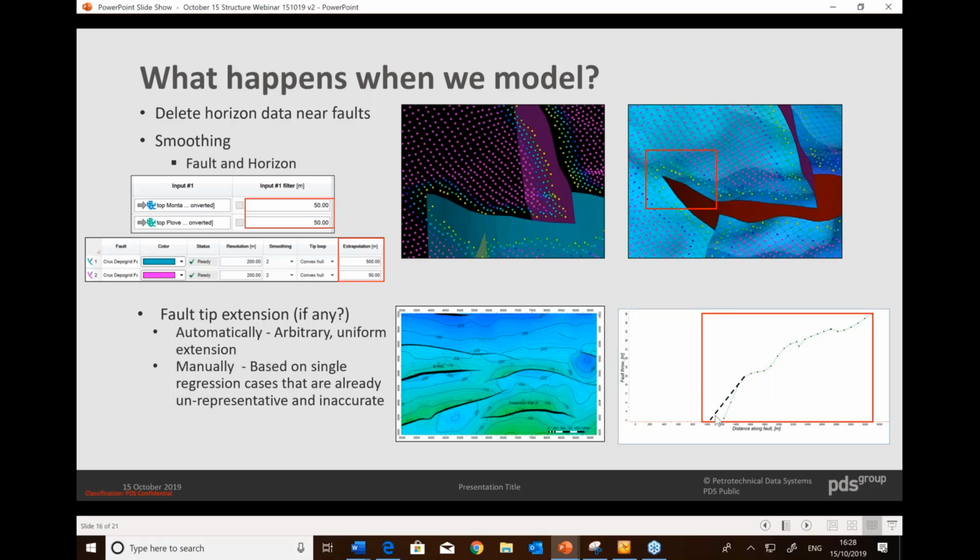So those of you that suggested 200 meters, which comes down into here, obviously based on perhaps this slope, that seems reasonable. But in reality, taking the full fault throw profile into account and taking the raw interpretation, what we actually see is an extension of this fault throw profile up to about 1 kilometer subseismically from that linear regression analysis. If we look at the Petrel default of 50, it's tiny. It extends no further than maybe this closing contour.